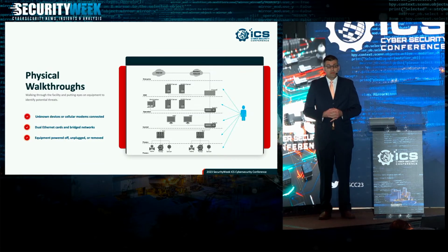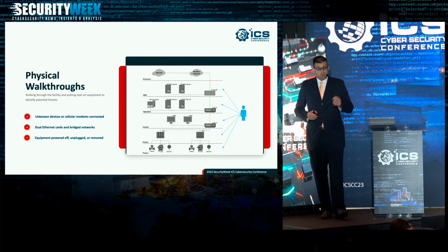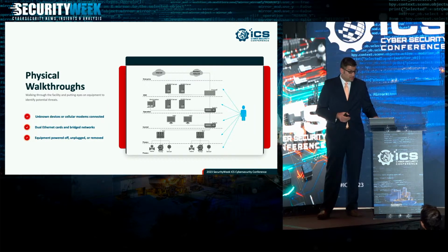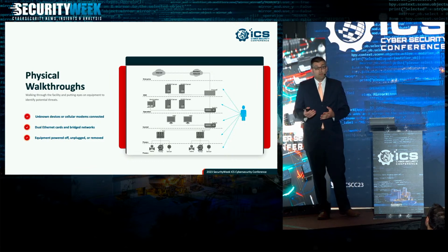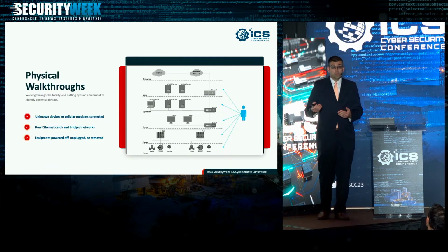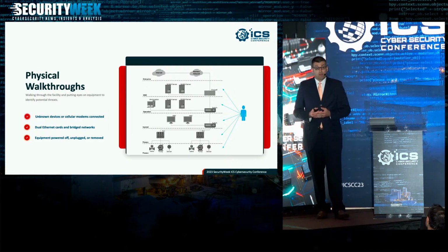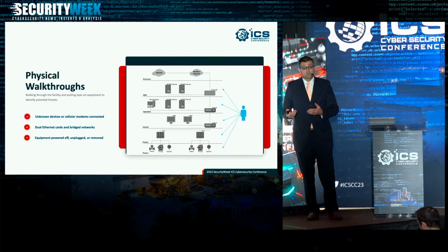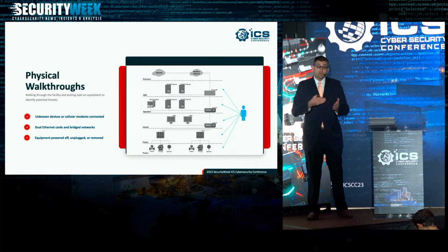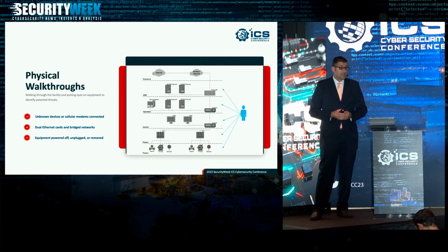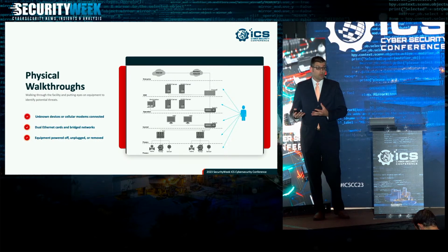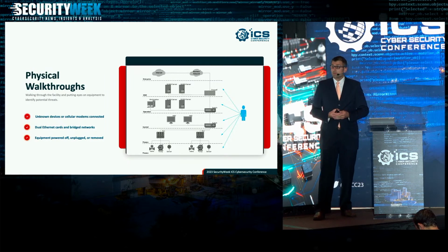One of them we found: we went out there and opened up a PLC panel, and I had assured people, you're not going to find this in our network. We open this panel up, and there's a cell modem sitting inside connected to a PLC. The vendor had actually left that in place so that they could remotely troubleshoot, remotely diagnose the PLC if there was ever an issue and we had to call them. Some people choose to have this in their environment. Contractually, some vendors may even require this. But it's one of those things that the same remote access method that your vendor uses could be exploited by a cyber attack. So weigh the risks versus the benefits and see, is this something you really want in your environment? That's one of those we had to go through and do.